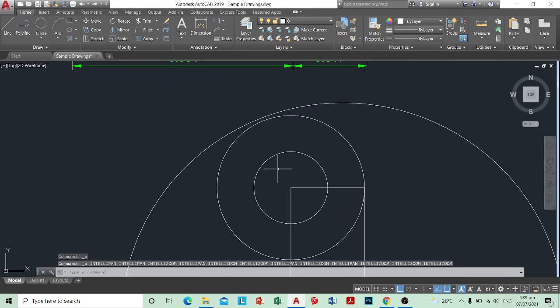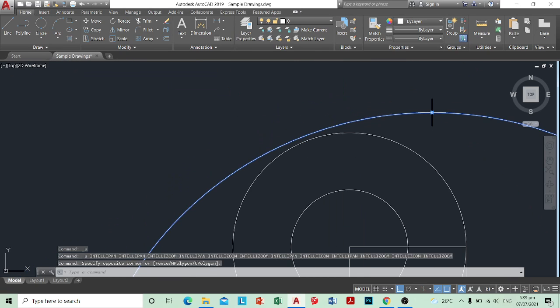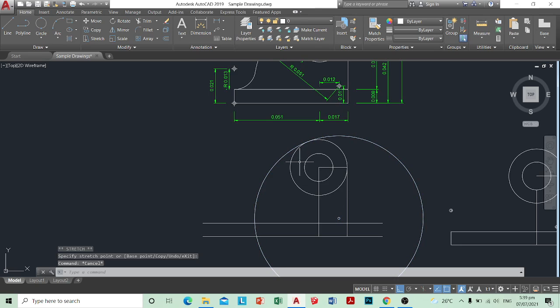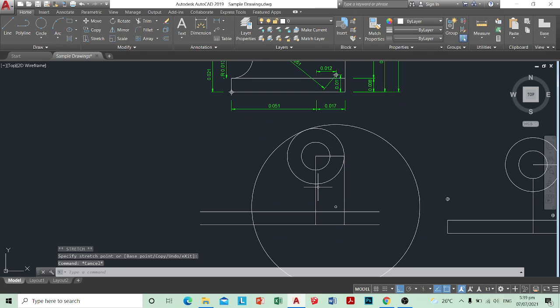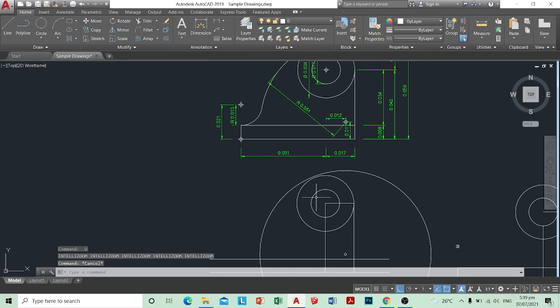This is the line I just entered according to my dimensions, but you can see there's a gap here. That's because we don't have the exact dimensions, but I'll just make it perpendicular to make it close. To make the object close, I mean. Next, we'll need to find this edge over here, which is 0.051. So I'll just offset.